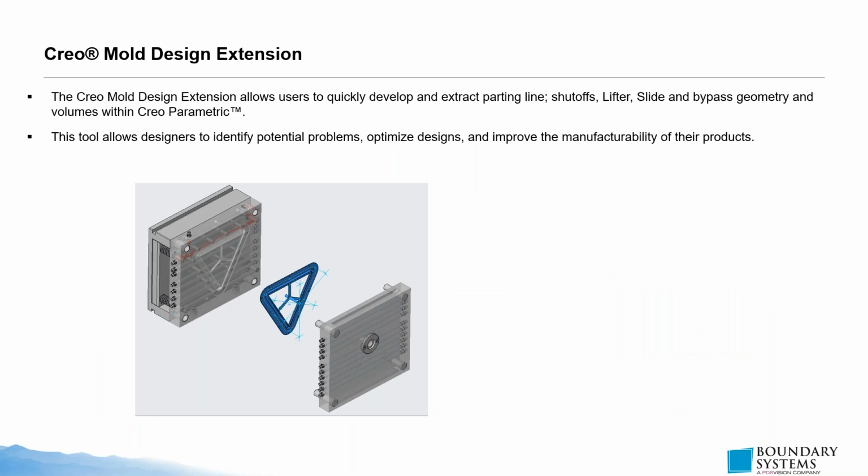Moving into the Creo mold design extension, it's an easy and seamless tool embedded within PTC Creo. One of its powerful uses is laying out tooling layouts, and evaluating and setting up parting lines, lifters, slides, and shutoffs. It's an embedded tool, especially if your native part is a Creo CAD file.